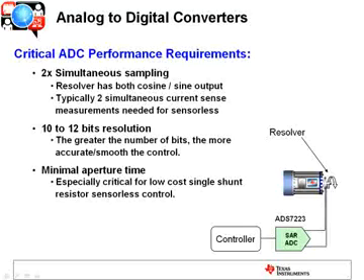And in the three legs, as the currents are changing, the window in which to get that measurement can become very small, just depending upon where the motor's at in the commutation. So you've got to be able to quickly get that reading and feed that back in order to commutate properly when you're using just a single sense resistor.